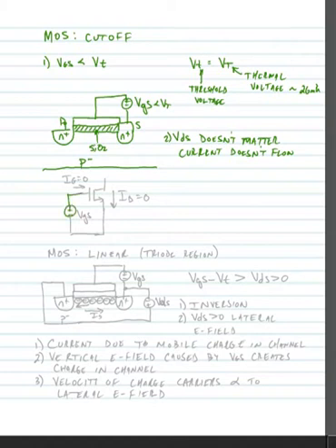So if we look at our transistor circuit model, we have a gate to source voltage that's less than the threshold voltage, and we would say that no drain current flows, or ID is equal to 0, and because we have an insulator between the gate and the source, we know that I gate is equal to 0. Now, what's becoming more problematic in fine line CMOS processes is that the gate oxide is so thin that you can get carrier punch through, which would mean that the gate current is not equal to 0. But this is a second order effect, and again, we'll ignore it.